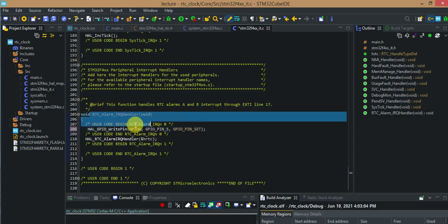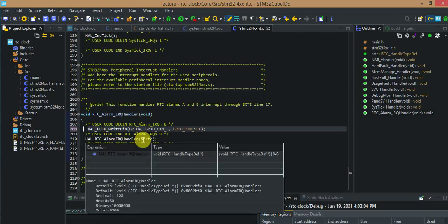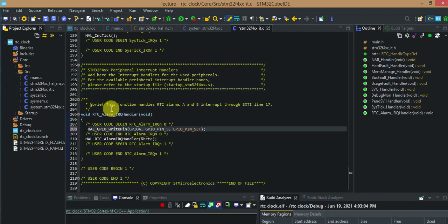But please notice that you cannot use any kind of delay inside this, because that delay will not work. This action takes a very small time period, because it just has to go to that line, touch it and come back, right? So that is a very small duration of time, and in that duration you can't use any kind of delay inside this function. So you people have to figure out how you are going to reset those LEDs.